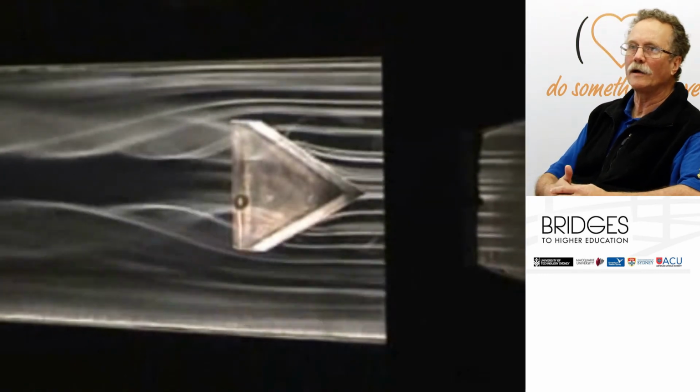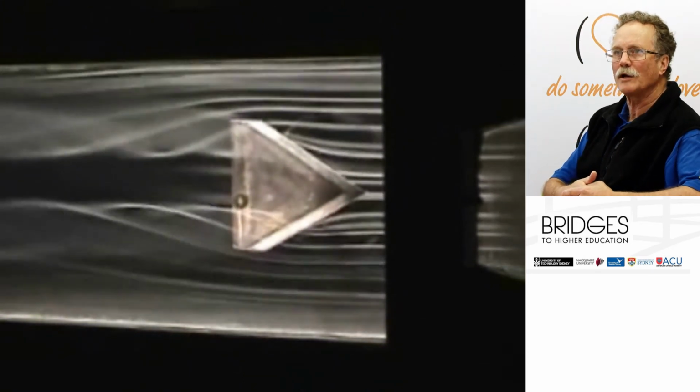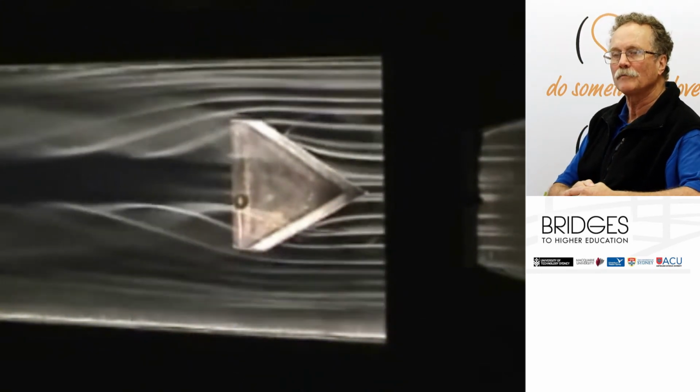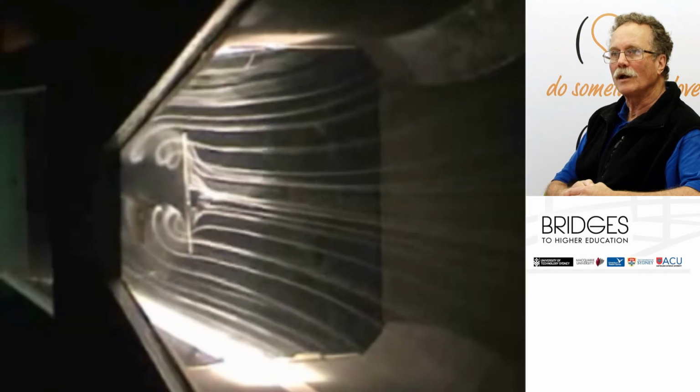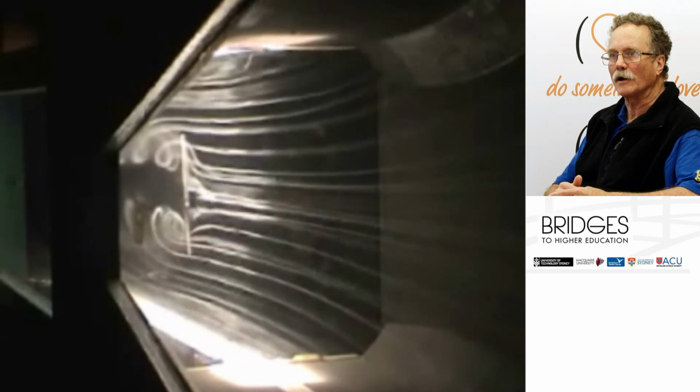The ultimate case is where you have the Concorde type wing, where those vortices are absolutely enormous, produce great big spirals over the top of the wing. And we'll have a look in a minute, you'll see a front view. So you can see the size of the rotations that producing lift creates in the airflow. Very large vortices, very large amount of drag.